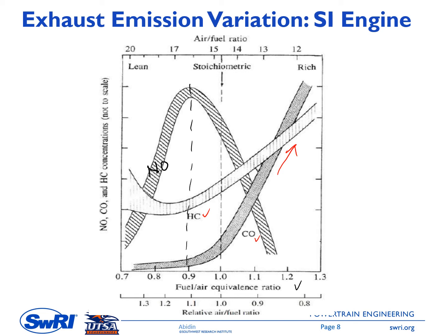So you will see later on that the NO emission is controlled by the temperature level. Which means the maximum combustion temperature will be around stoichiometric condition here. Okay, this NO emission is also governed by the amount of air.